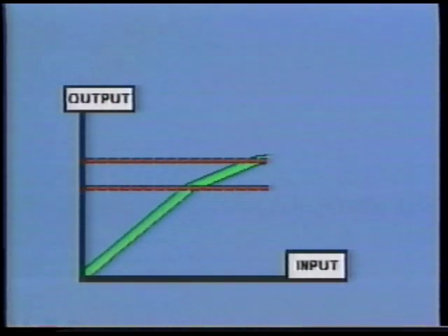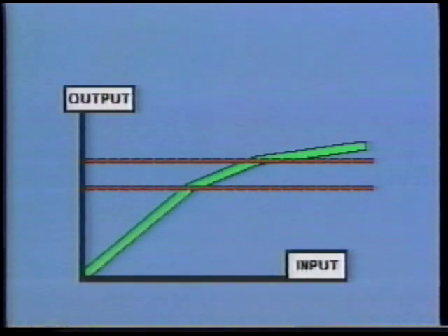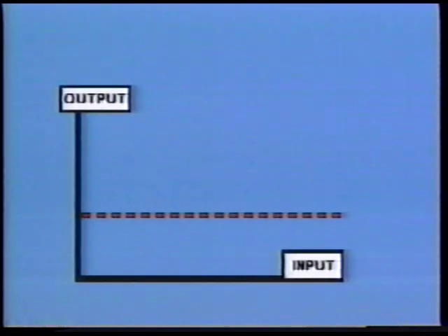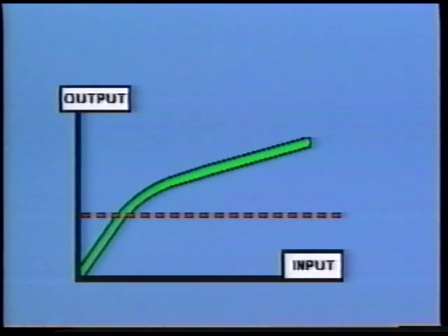Some compressor limiters have 2 knees. The first is set for a lower threshold and a gentler ratio, and the second has a higher threshold and ratio. What happens is that gentle compression will occur most of the time, and the highest peaks will be limited. A few small compressor limiters, called over-easies, have variable knees that gradually increase the ratio as the signal rises above the threshold. Basically, the louder the input signal above the threshold, the higher the ratio of gain reduction.